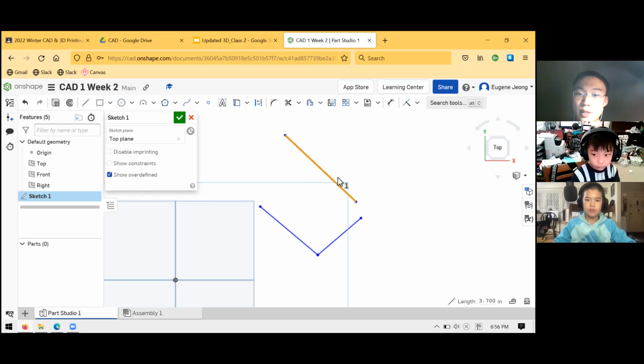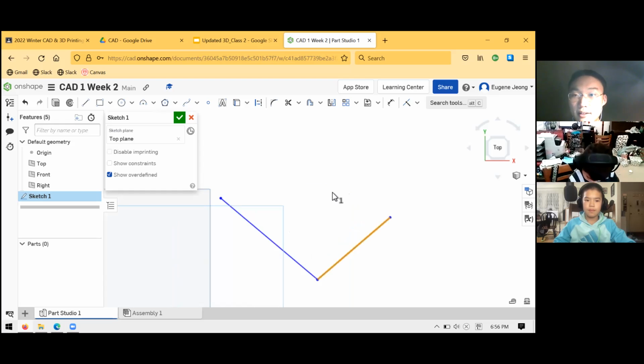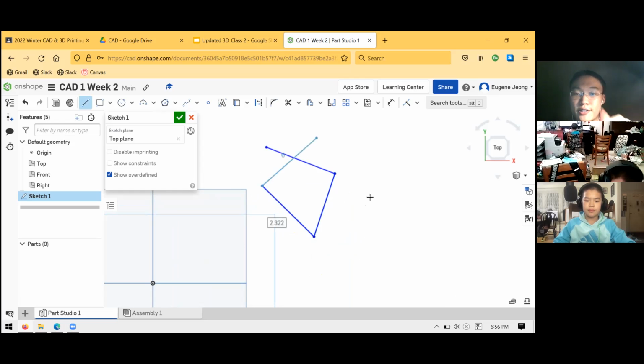And you know it's selected because it turns yellow. And once it's selected, to get rid of something, you can just hit delete on your keyboard. It's different from the backspace. There's a delete key, which is sometimes a cause of confusion. I guess backspace does work, learn something new. But you can delete entities just by selecting them and hitting delete. I'll create some more lines just to show you.